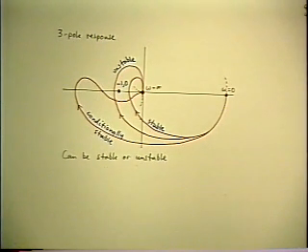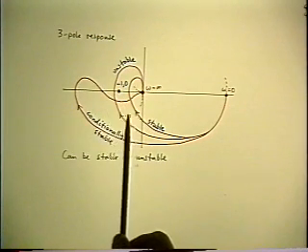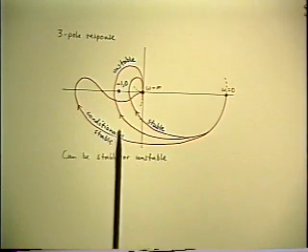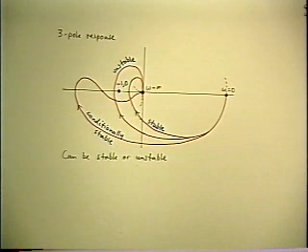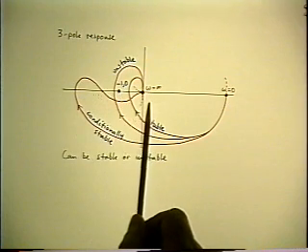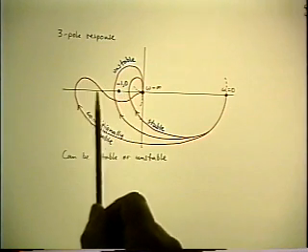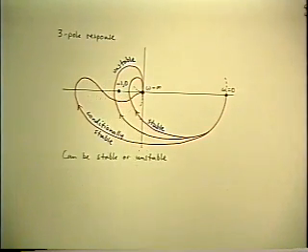and that may be all right, but the problem with it is that if it's stable under a normal configuration such as the one I've shown here, it could go unstable at lower values of gain, because a lower gain would make the contour get smaller, and if it gets smaller in such a way that this loop went around -1, it would go unstable at a smaller scale. Now that's hazardous, because you can visualize a whole lot of abnormal conditions, or maybe not so abnormal even.